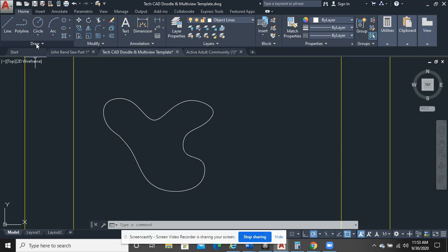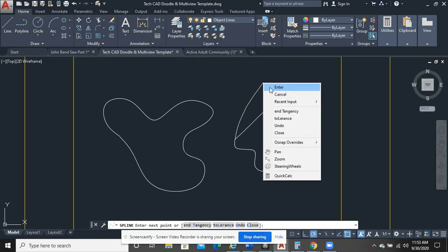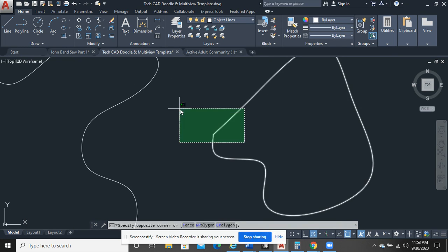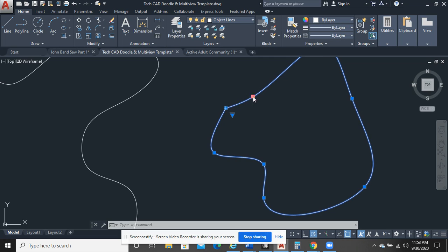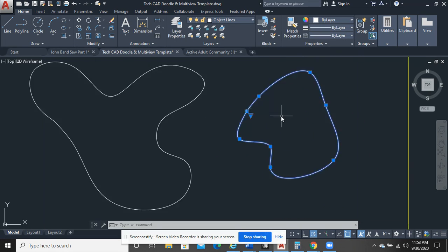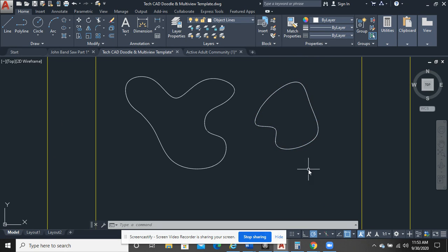Again, just to see where I did it, I hit the draw button, the drop down, I click Spline Fit, and I can just, like I said, go ahead and manufacture just about anything I want to. Students a lot of times have used this as a real cheater in doing logos and stuff like that. And even in 3D work, I think a lot of people tend to look at this and think it's a magic bullet, but it's a tool that you just don't use very often.